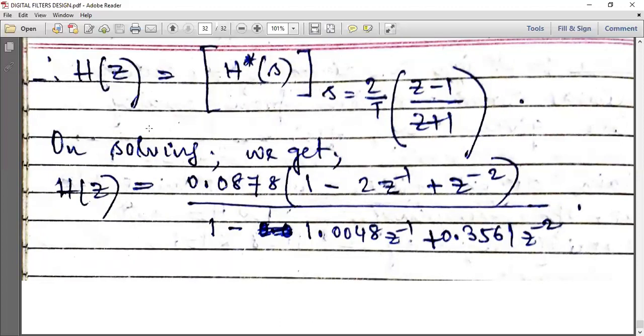However, Hanning window generates less ringing in the side lobes, and so it is most widely used. Means Hanning window is advantageous than Hamming window. Clear? The Blackman window reduces the side lobe level at the cost of increasing transition width.